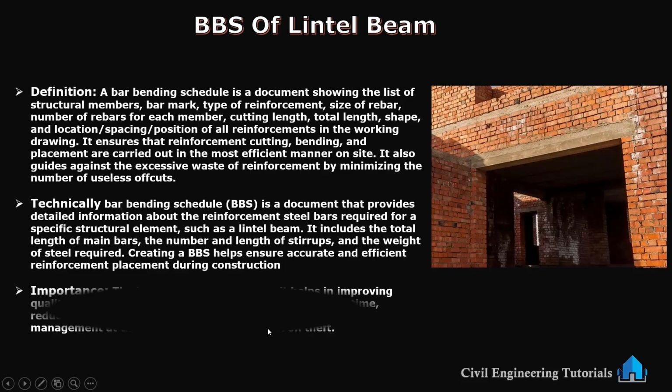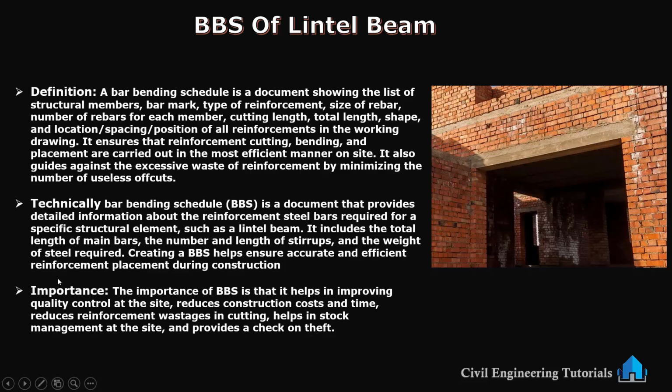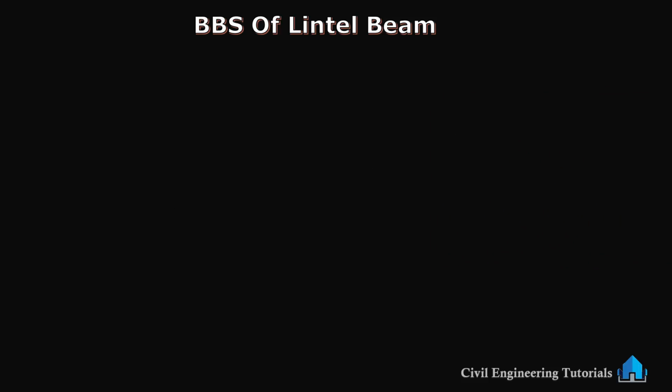So, what is the importance? The importance of BBS is that it helps in improving quality control at the site. It reduces construction costs and time, reduces reinforcement wastage in cutting, helps in stock management at the site, and provides a check on theft. So, hope you understand the definition and importance of BBS.